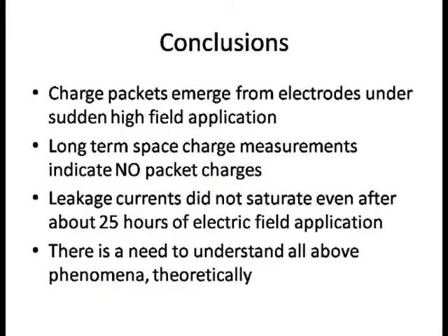Even if you go to 100-200 kilovolts per mm, there is no space charge observed. So conclusions: some charge packets emerge from electrodes under sudden high electric field applications. Long-term charge measurements indicate no charge packet movement.